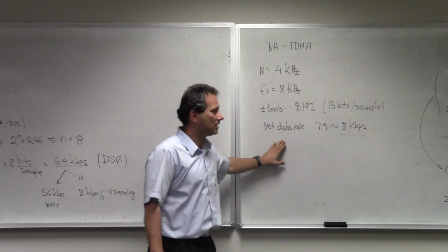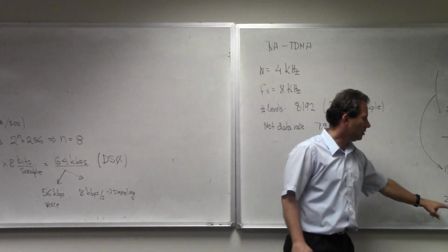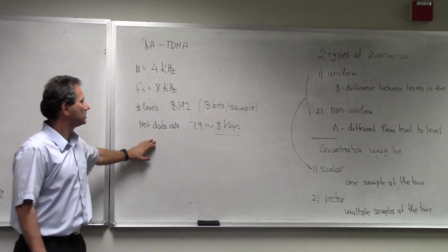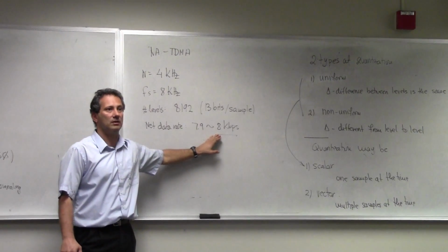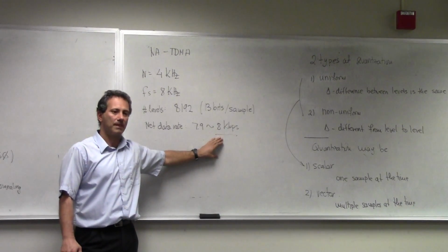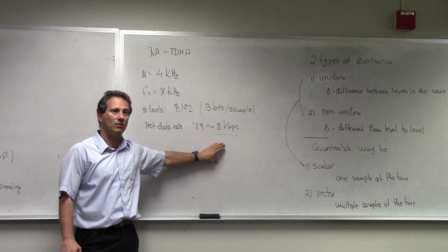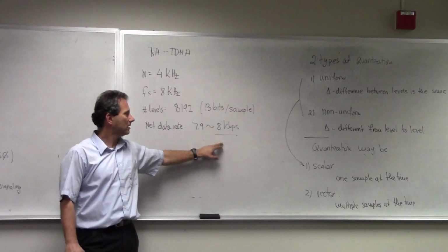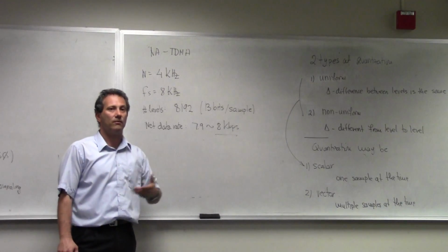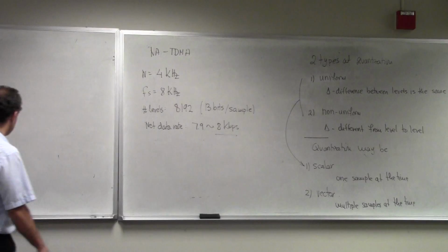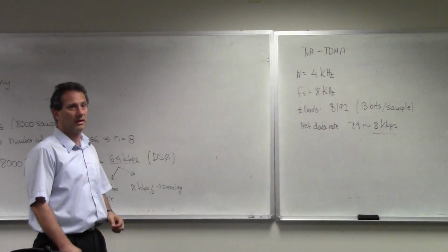This is an indication of how much you can gain by utilizing vector quantization. Contemporary systems go even below. The modern AMR, adaptive multi-rate vocoder for GSM, or wideband CDMA for that matter, can go all the way to roughly 4 kilobits per second, achieving 16 times compression relative to the regular PCM.